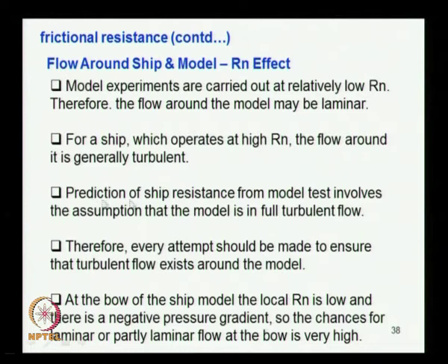So, prediction of ship resistance from model test involves the assumption that the model is fully turbulent. That means, to achieve kinematic similarity, you have to generate turbulence around the model also. So, every attempt should be made to ensure that a turbulent flow exists around the model. We have some techniques to generate turbulence around the model to give more resemblance to the flow conditions around the ship. Only then will the prediction of resistance from the model become acceptable when it gets extrapolated to the prototype.